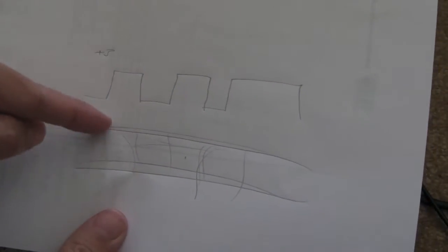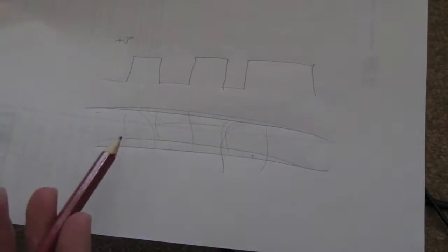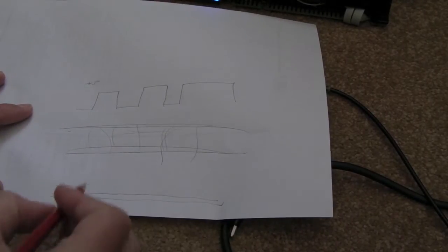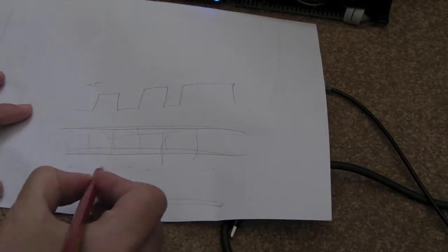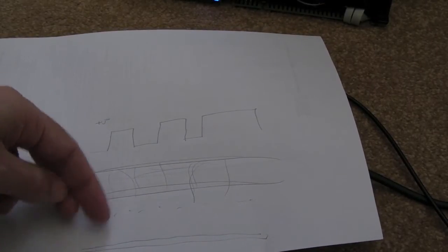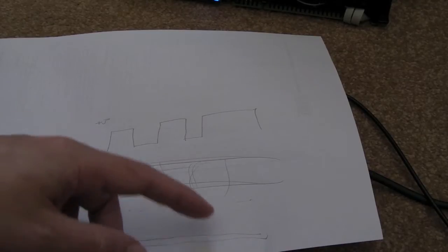But it's interesting. The key, I guess, is understanding you get this logic level here. And what I think we're going to see is on some of the data pins, if that's your ground level, you're going to see something like that, very low, instead of up at that level there. What that indicates is probably some sort of pull-up resistor or something internally has failed. It might be on one or more of the data pins. So let's give it a go now. I'm just going to connect it to the scope. I'll point you to the scope rather.